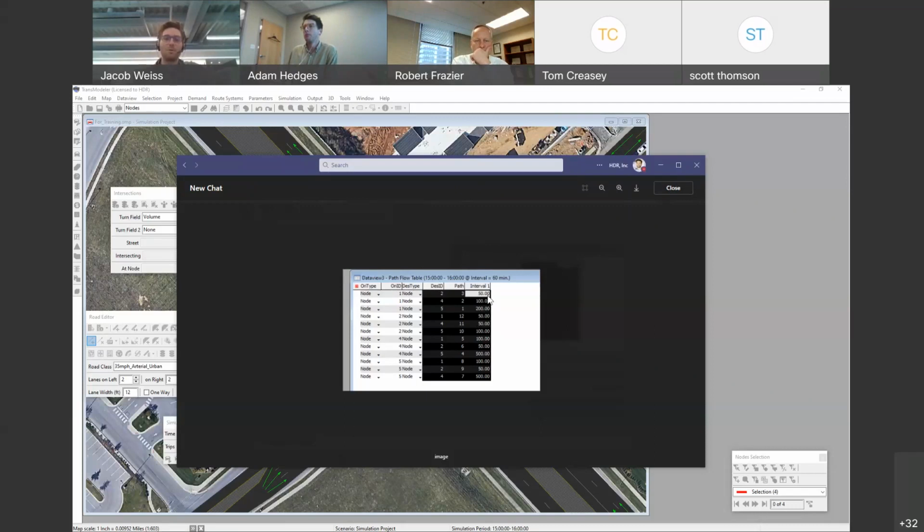If you make it a more unsaturated condition and let it use distribution percentages to route that volume through the network, you can take that CSV or bin file and develop a matrix from it that you can plug back in, so that when you look at a different alternative, you're not breaking your network, and those ODs can stay on the outside and not be messed with. Good.